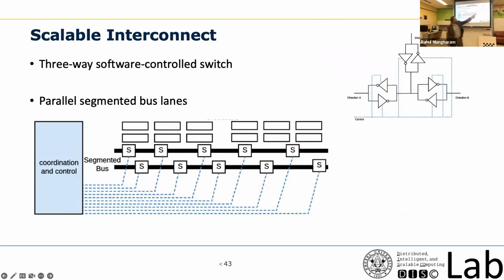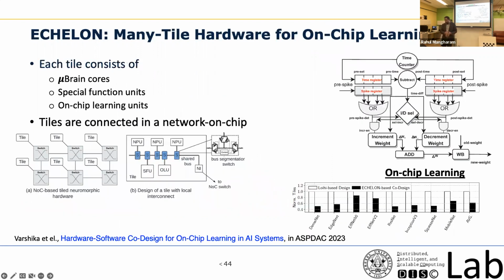And as I said, our switch is something like this. It's a very simple switch. Together with IMEC, we designed that switch, and we designed that entire architecture on hardware, and we got very good results. Building on top of it is where we talked about on-chip learning. Remember, we talked about how you can do STDP-based learning.